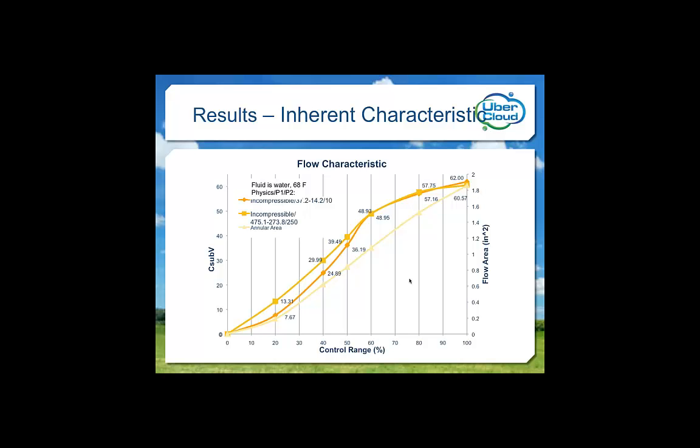While 11 control positions are ideal to fully map the characteristic, 5%, 10%, 20%, and so on, I ran just 6 design studies to find out if virtual valve testing is a viable way to verify a valve design. This was simple. Change the position of the trim in Inventor, activate SimCFD, and tell the program that this is a new design study with the same settings as another design study. All this takes just a few minutes for each control position.